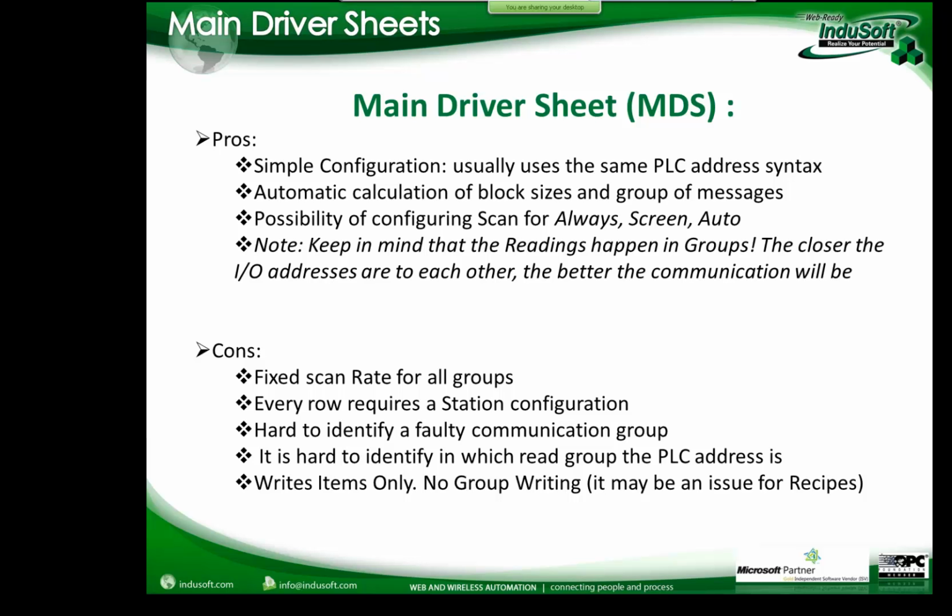Okay, so when you're configuring your PLC program, we highly recommend that you keep in mind that you're going to talk to an HMI. So the addresses or the tags that you're going to use to talk to the HMI, keep them close, keep them together. Make one array on the ControlLogix, or on Siemens, keep everything in the same DB or in as few DBs as possible. If you're talking about Modbus, you keep the 40X or the 0X addresses closer.